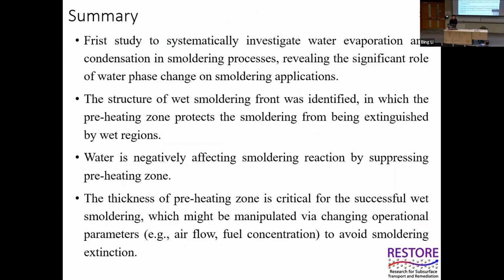So in summary, this study is the first to systematically evaluate water evaporation and condensation in the smoldering process and reveal a significant role of water in smoldering applications. The structure of the wide smoldering front was identified, where the preheating zone is crucial for successful smoldering. And water negatively affects the smoldering reaction by suppressing the preheating zone.